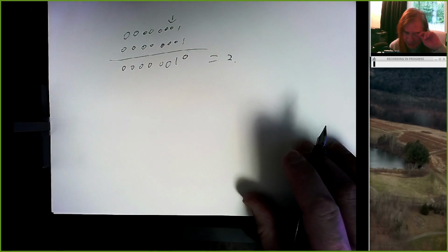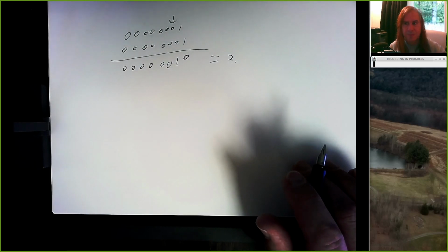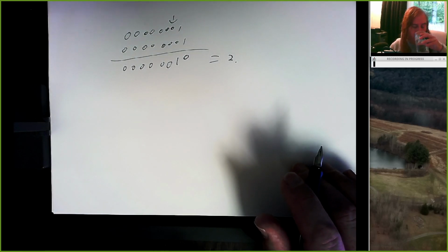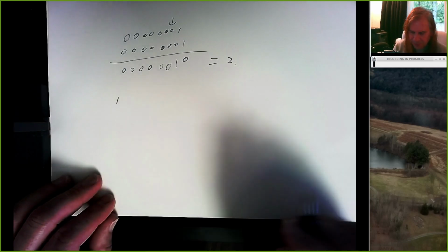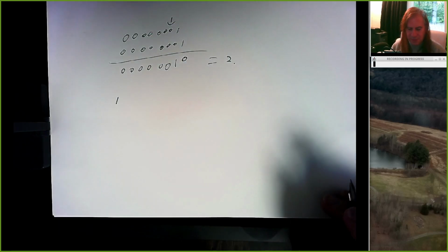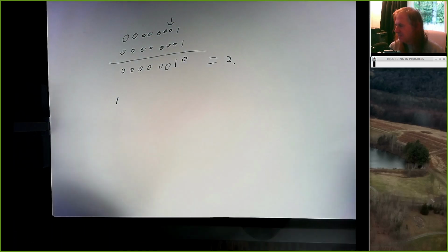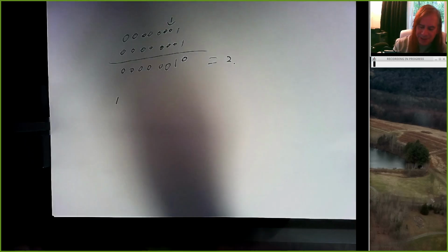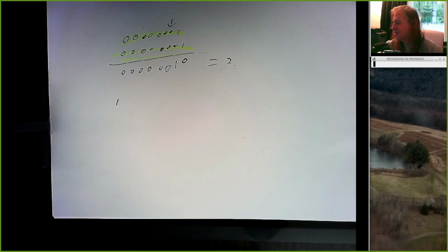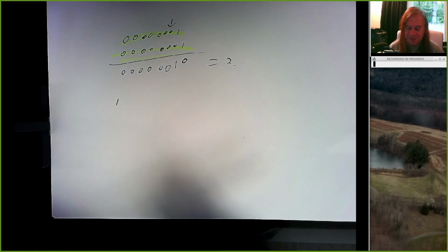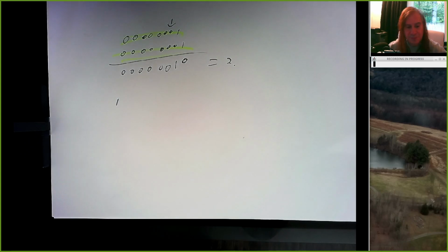Gotcha, all right. Now if we try the carry part, all right, I see now. And one of the keys is you've got to make really sure that you're using the right number of bits. So if we're doing 8-bit addition, go ahead and put in those 7 zeros in the front. Especially when you have negative numbers, those will make a big difference. All right, I see. I see how I got it wrong.